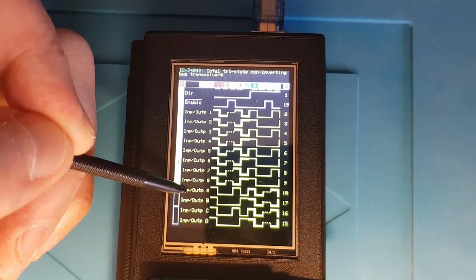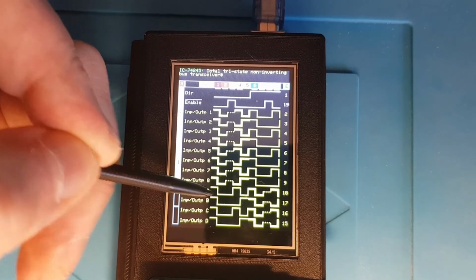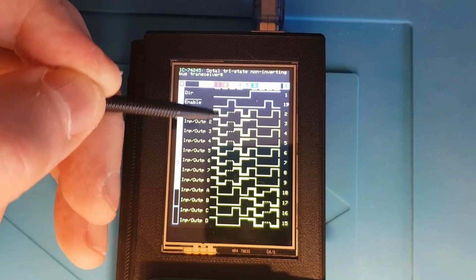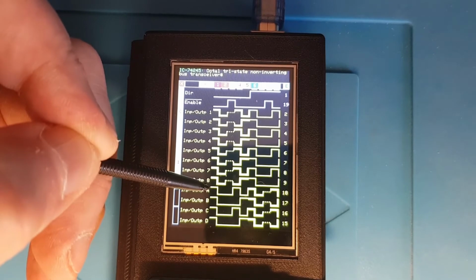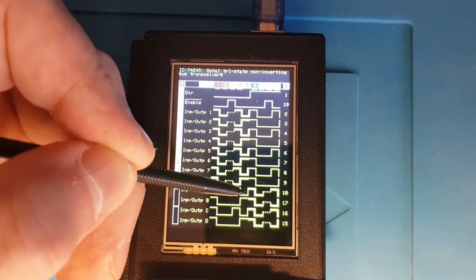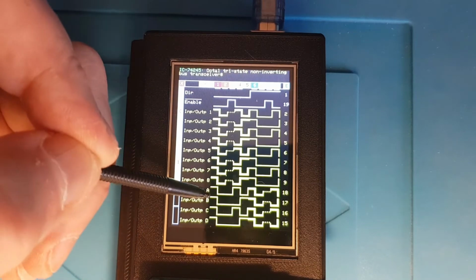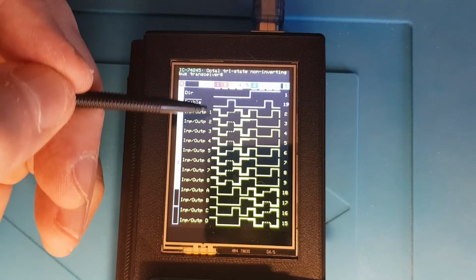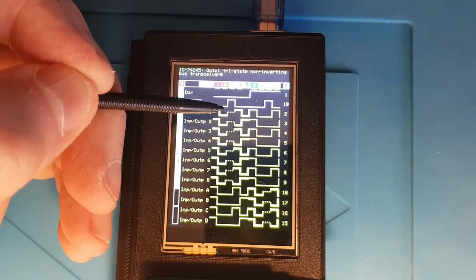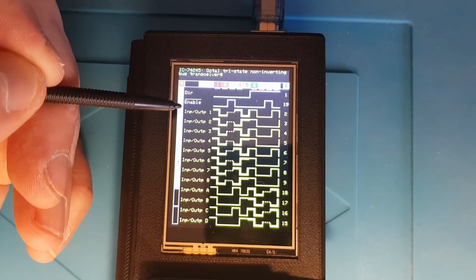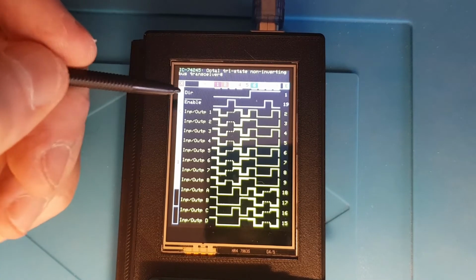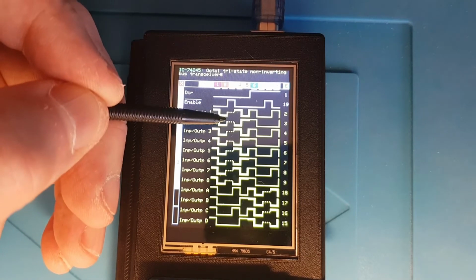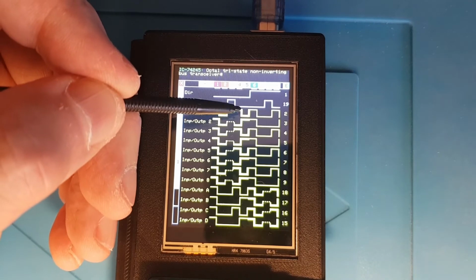So in this case, because this line on A is thin, we've got high in the first step, and that's going to input output 1, which is showing as a thicker line. So these inputs all the way up to step 5 are being manipulated on input output A and reflected on input output 1, and you can see that because the enable pin, which is active low, is raised here, the outputs on the transceiver are disabled and therefore go into high impedance state, and that's why we've got a thick output line that's high, then low, then goes to high impedance state, then goes back to high, then back to low,